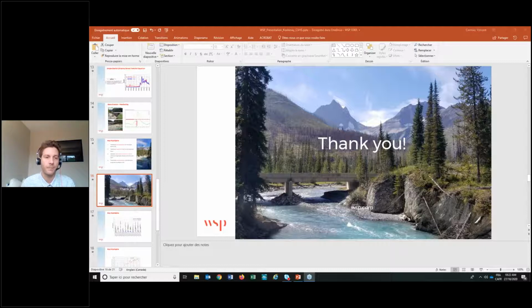Okay, thanks. One final question from Xavier Pinto. Your rating curve was a theoretical curve extracted from HEC-RAS. Normally you would need to use 10 points to develop a rating curve. Do you think you would have got better results following this approach rather than the 2 points that were used?